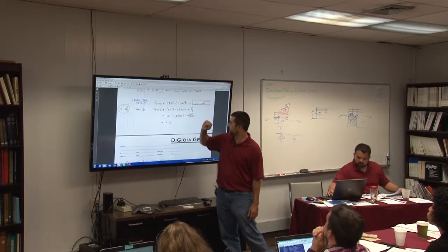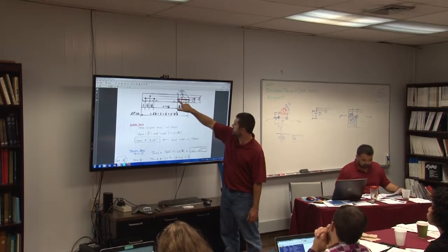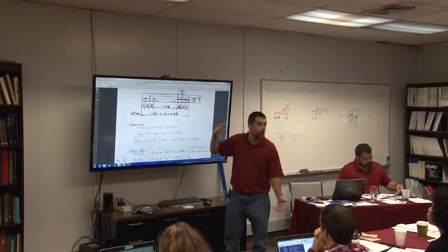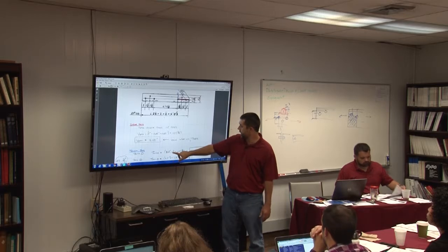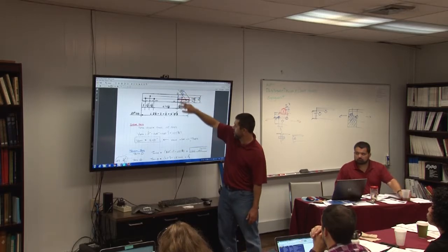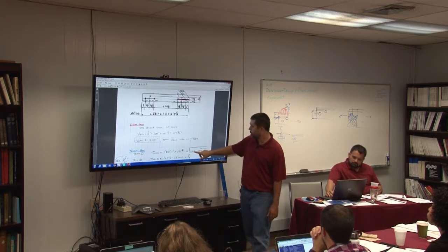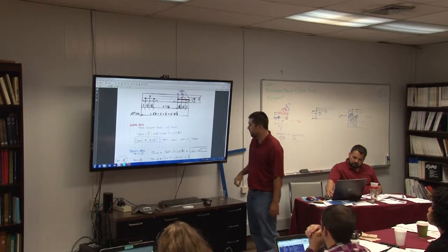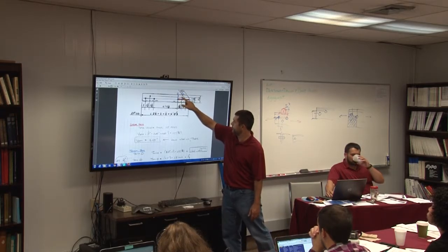For number 1, basically, can you scroll back up to the top for a second? I'm going to say that this distance from this bolt to the end is 2.5 minus 1 inch. It's 1.5 inches, but I've written it down as 2.5 inches minus 1 inch, so that's that length, minus 1/2 of a hole gives me 1 1/8 inch here. The other option is this.